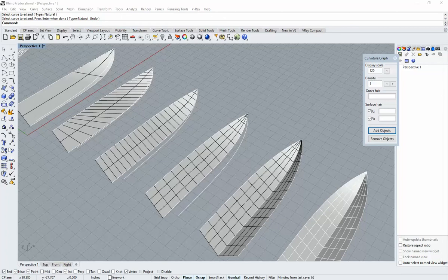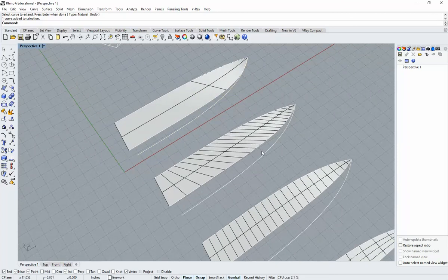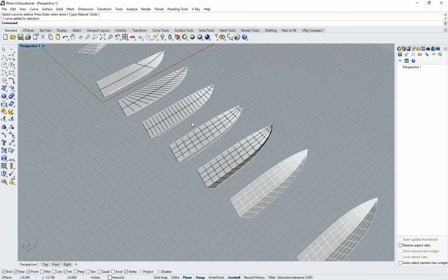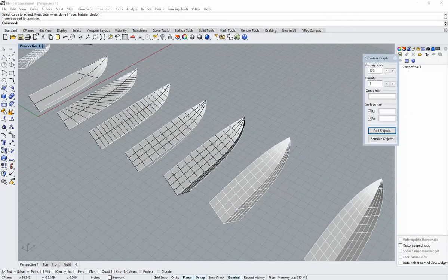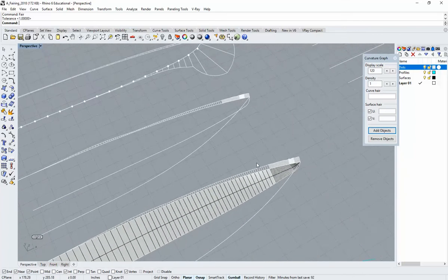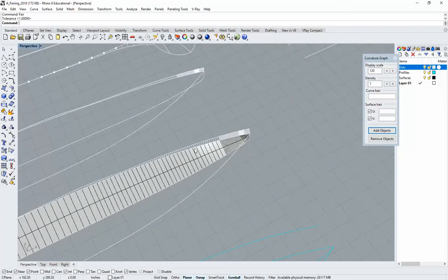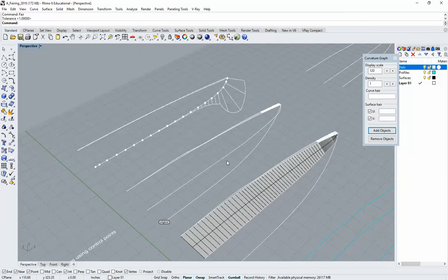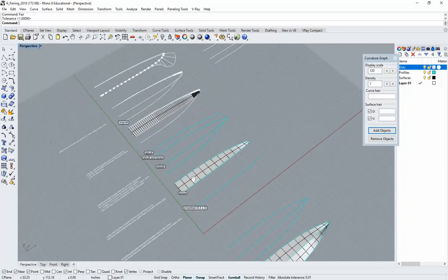Over here, how we started was to just draw the lines cleanly. We drew them with control point curves with very few points, 4 points in this case and 5 points in the other. And then we went through the process of rebuilding them and increasing the density of the surface. That was the result. Here it's slightly different. We went through a process of tracing out an image, which is okay, but we then have to go through and clean up and fix the result of that in order to produce surfaces that are back to what we're looking for.